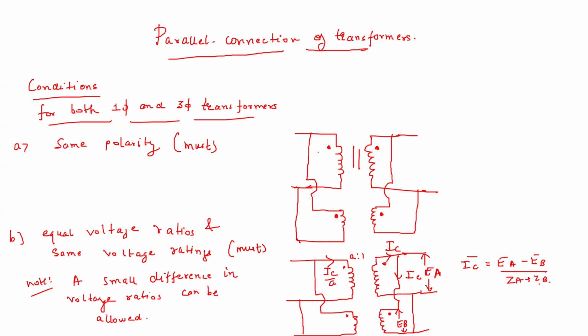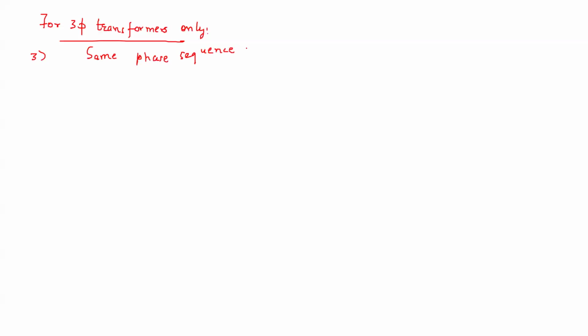Now there are some conditions which are valid for only three-phase transformers. The conditions for three-phase transformers only. What are some more conditions? It is the same phase sequence, because in three-phase the phase sequence also matters. Same phase sequence is a must condition.